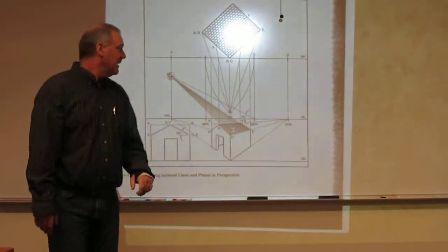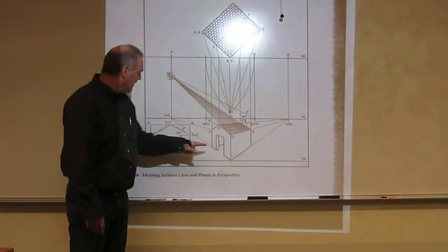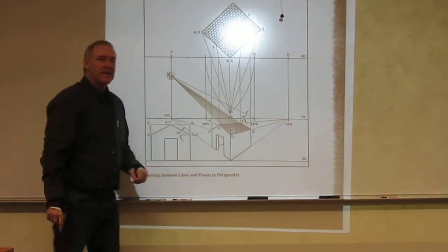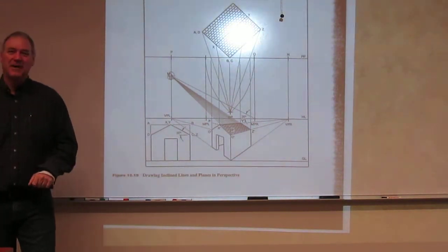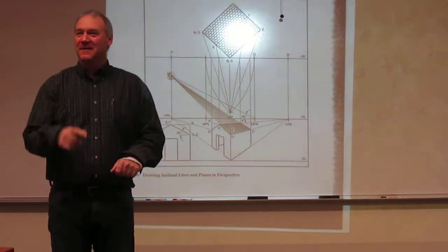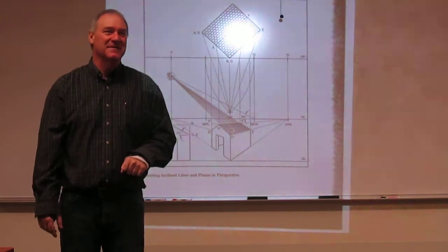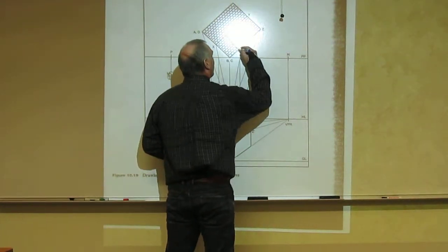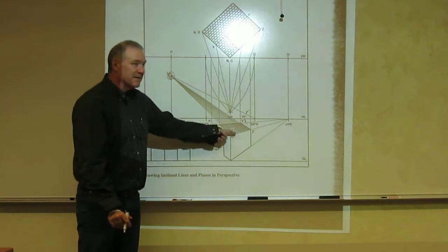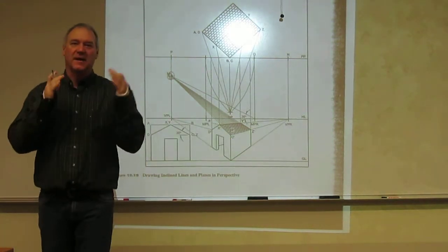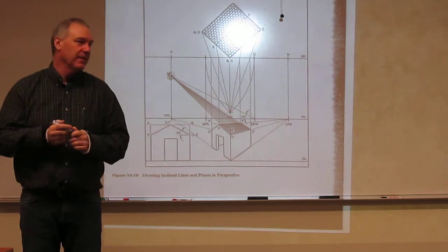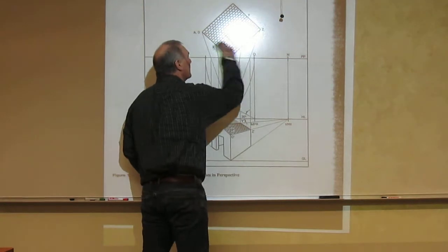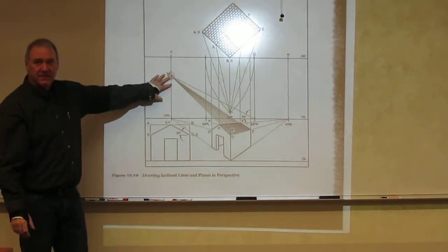Now, if you don't have two of these lines, like here and here, it's on here. This one you do, because it's right there and right there. Keep in mind, you're a drafter. You got a pencil and eraser, and you got the line command and the delete command. You can add lines to this. Okay, if I did not have one, I'd come in here and I would draw one, and then project it onto this view. Now I have two parallel lines. I can project them and find that vanishing point. And then I just delete it back out. So we're going to cover this a little bit today too.